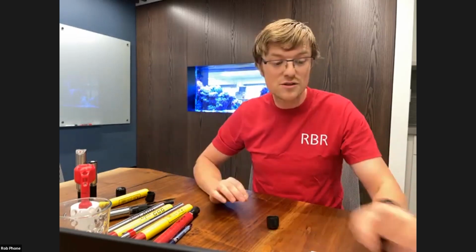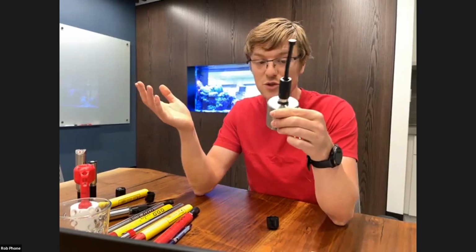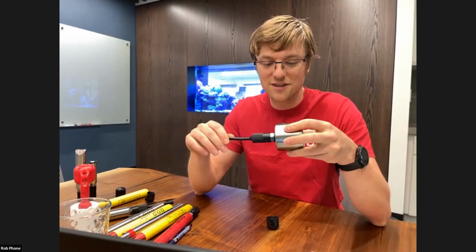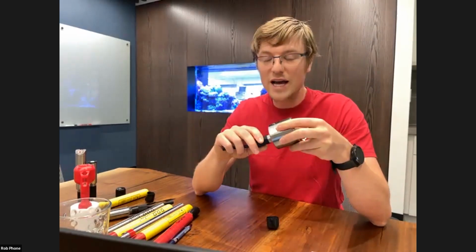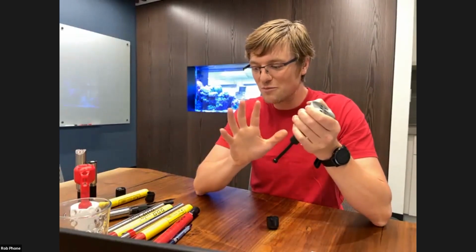So Kelsey asks, I work for AGO Environmental. We make winches for deploying oceanographic equipment. Can you share info about stuff like how fast these sensors need to be pulled through the water column, what kind of cables they work with, etc.? Yeah, so certainly our cabled sensors, so this particular sensor and all of our CODA series, they communicate over RS-232. Over a variety of baud rates, depending on how far you want to send that signal and how fast you want it to sample. As for rates, that would be mostly driven by the time response.